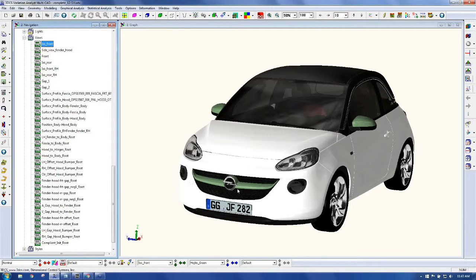When you're importing your data in, you have an option in KeyShot, and some of these other software too, to keep the coordinate system of all the parts, which they're going to be imported then in the exact same location and coordinate system as they were in 3DCS. That would be called keeping the original in KeyShot. Otherwise, each part, as you import those in, are going to be put to the center and put to the ground. So they won't be in the actual vehicle position or product position. They will be in a 0 position. So that's one thing to remember.